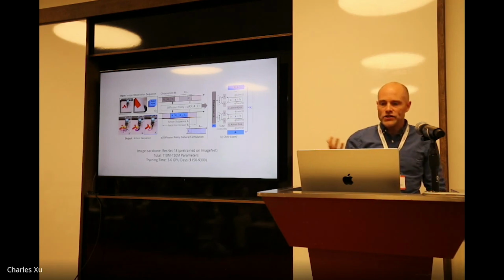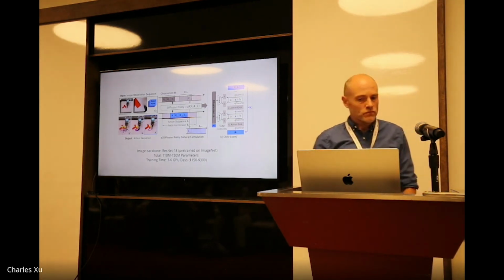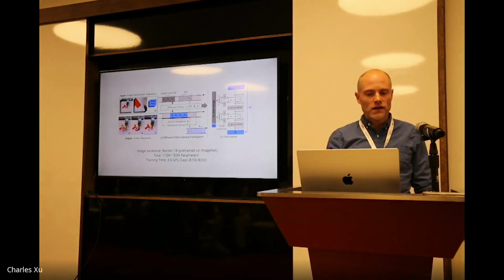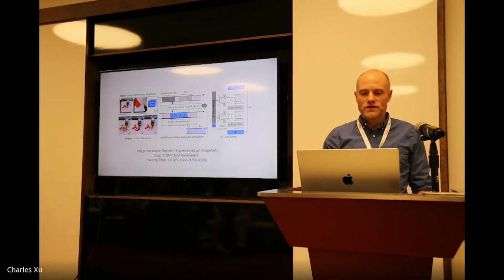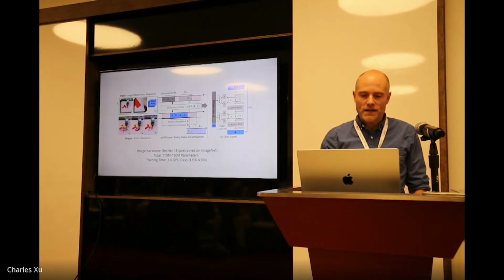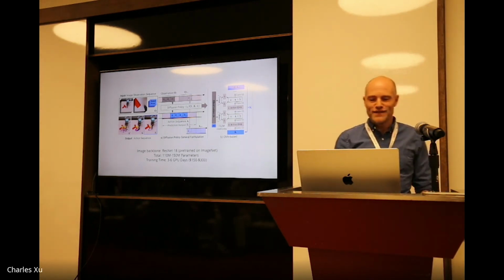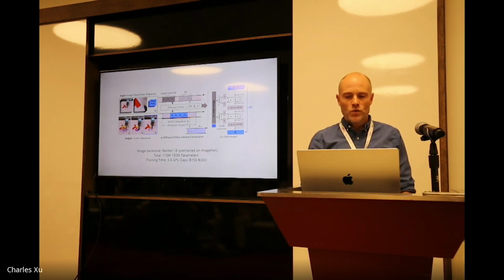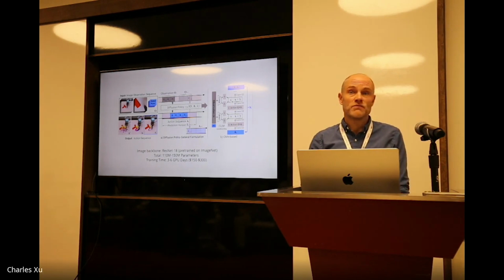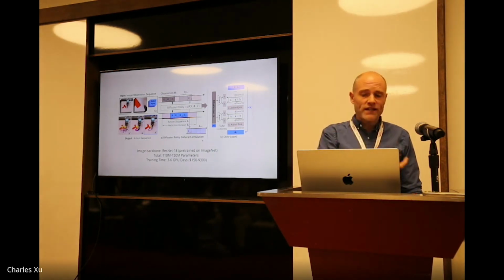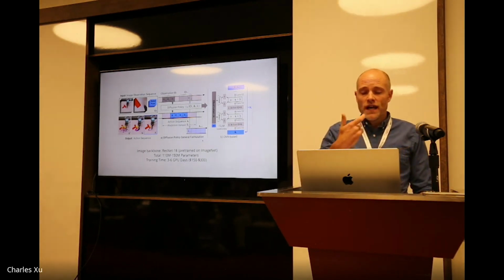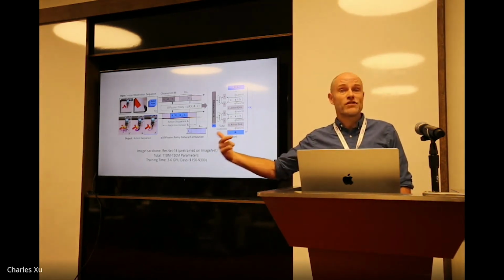Okay, so the architecture of diffusion policy is somewhat standard, and you know, it's what you would do if you were to put all these tools together, right? So ResNet backbones. A few people asked me about how many parameters in the single skill task. We tend to have between 110 and 150 million parameters. We're still using UNets in the denoiser for diffusion, and importantly it's taking a history of observations and predicting a forecast of future actions.